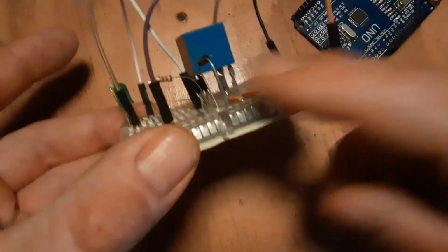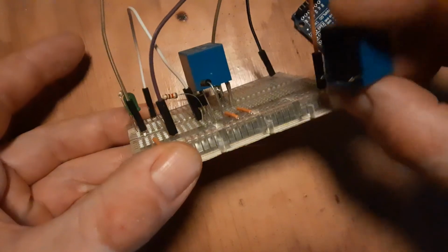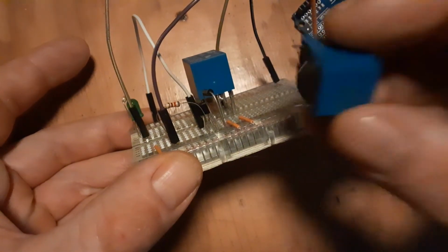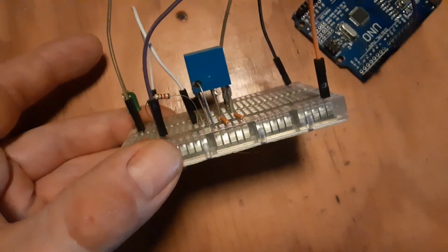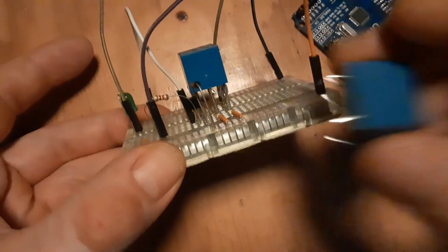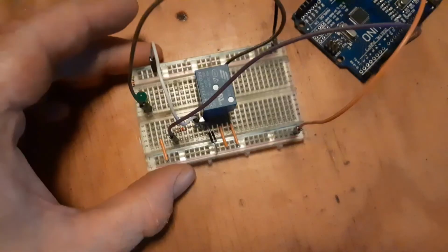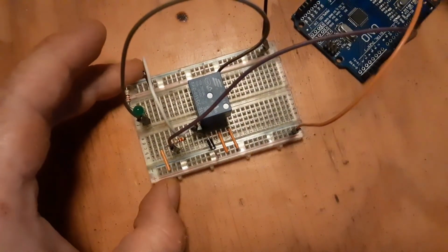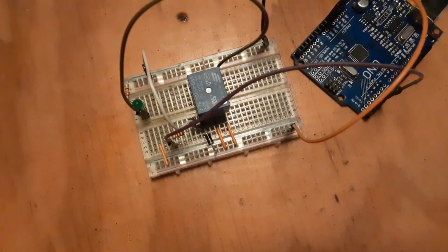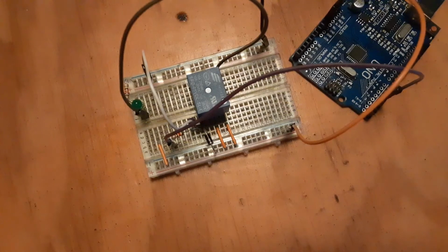Oh, and this one, compared to the other one, on one of my relays, I just soldered on some long leads that are plenty long enough to bend easily and seem to work with a breadboard a lot nicer for testing things. So we can send a big current through it, but in this case, I'm just sending 5 volts through like the earlier example. Same code running it. This pin goes high, waits for about half a second, then goes low, waits for half a second, and keeps toggling.